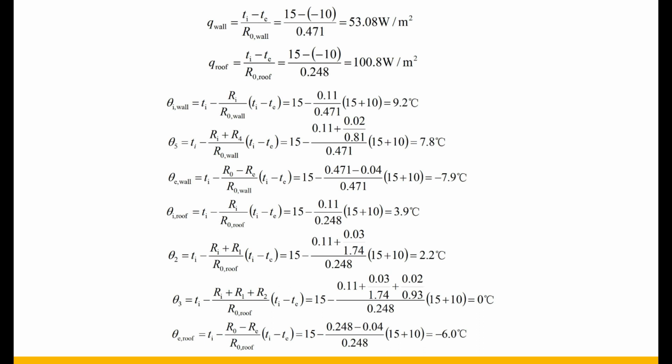It can be seen from the calculation results that the inner temperature and the inner surface temperature of the roof are larger than that of the brick wall, also because the thermal resistance of the roof is smaller. Based on this conclusion, you can choose the appropriate envelope structure material for building design and compare the heat loss by using different materials or different structural forms to see which material has better thermal comfort for the envelope structure form.